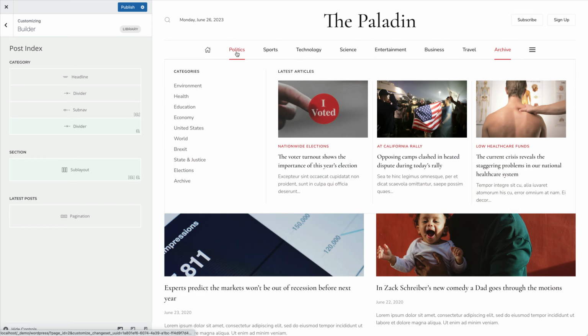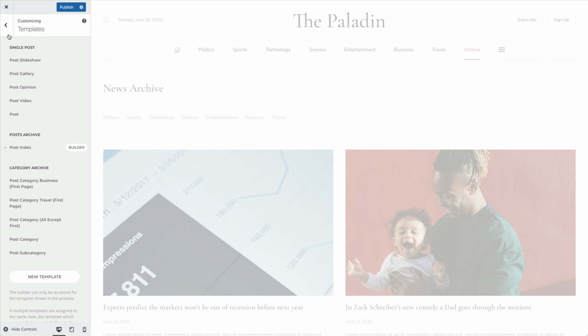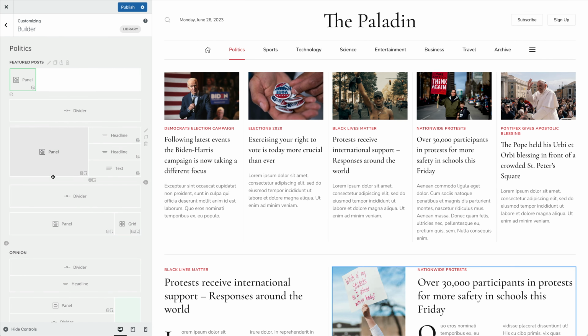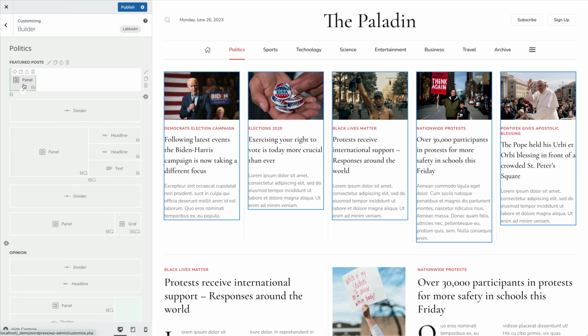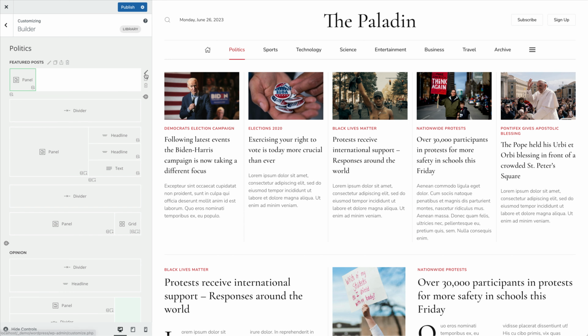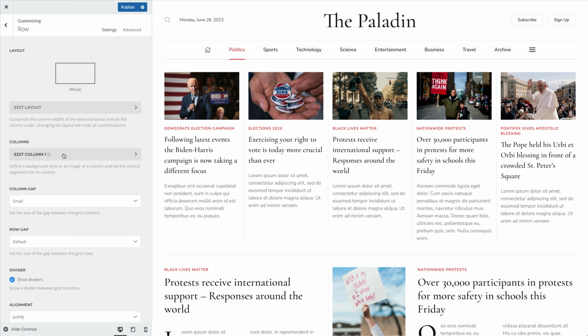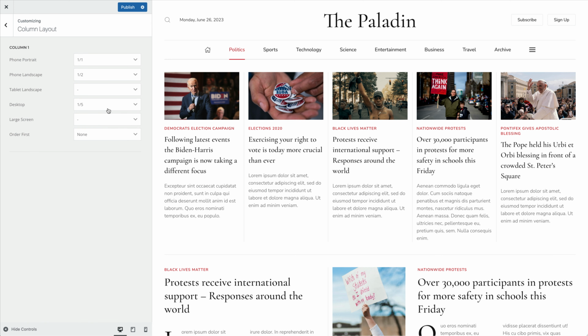Finally, if you multiply a column, the other columns defined by the row layout are still present. That's why for a layout with just one repeating column, as in our case right now, the row layout has to be set to whole. You can then set the width for the multiplied column by editing the layout. This will define the number of columns after which they wrap into the next line. Of course, in advanced cases, different columns can be multiplied using a row layout with more columns.